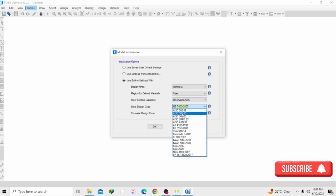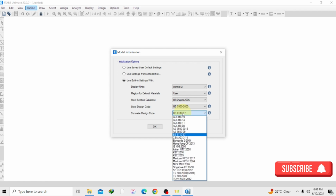We also have the same codes here, AISC code, a whole lot of codes. We have the Eurocode too here, but I'll be using the BS code. So based on what you are using for your steel design, just select that one. And we also have the concrete design code. I'm going to go with BS 8110.